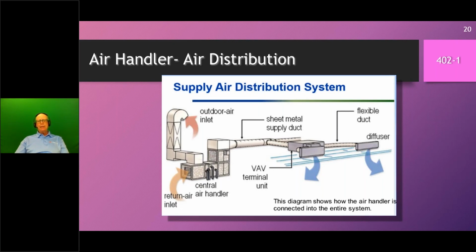So basically we've got an outside air inlet, and then we mix that outside air, fresh air, quote unquote, with return air coming back from the rooms. And then that central air handling unit is going to have a cooling coil, and then it will have a fan capacity control mechanism of some type, which today is going to be a variable frequency drive.